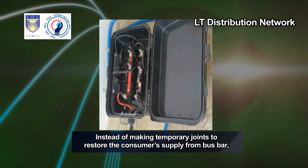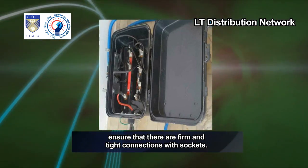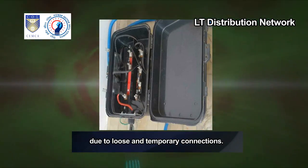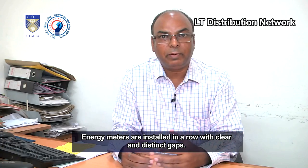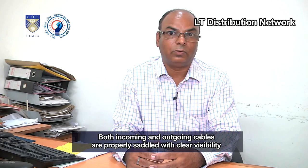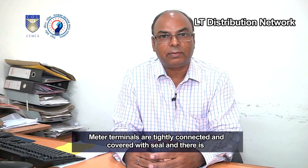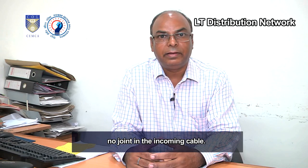Instead of making temporary joints to restore the consumer's supply from the busbar, ensure that there are firm and tight connections with sockets. There should be no jumbling of wires, which is a major cause for breakdowns due to loose and temporary connections. The following are the corrective measures. Energy meters are installed in a row with clear and distinct gaps. Both incoming and outgoing cables are properly saddled with clear visibility from their feeding points. Meter terminals are tightly connected and covered with seal, and there is no joint in the incoming cable.